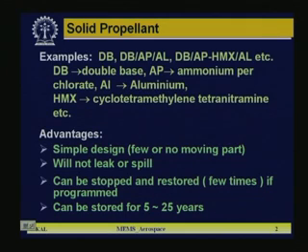So the advantages of solid propellant are: it is a simple design, with few or no moving parts, and it will not leak or spill. If it is a liquid, there are chances of leaking or spilling over. It can be stopped and restored a few times if programmed, and can be stored for 5 to 25 years without any deterioration of the material. So this is the advantage.